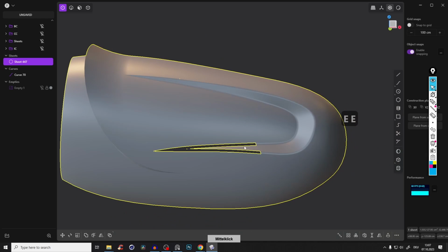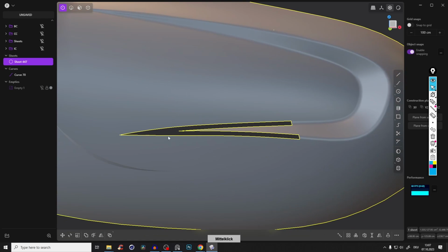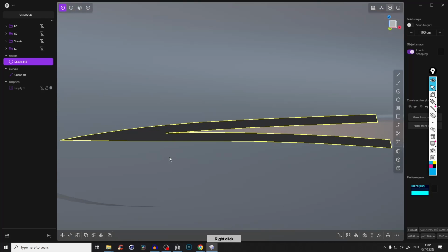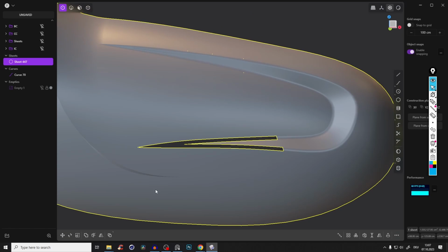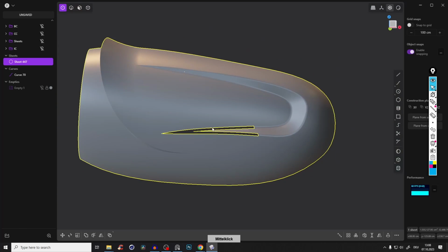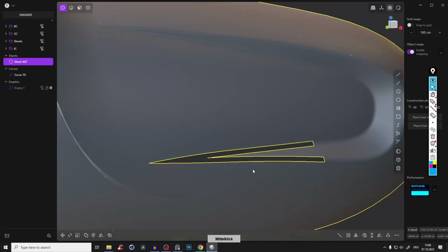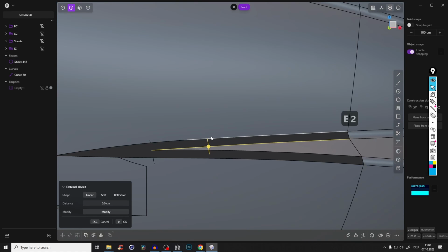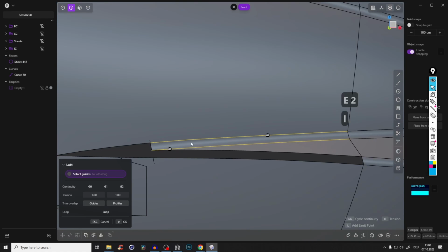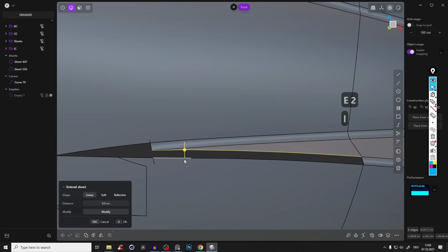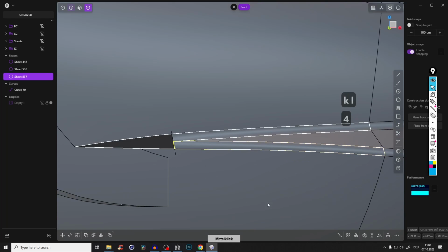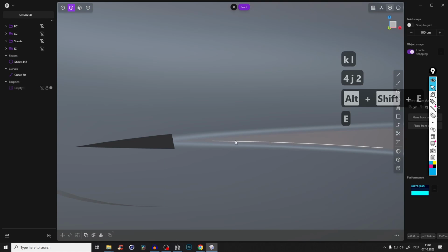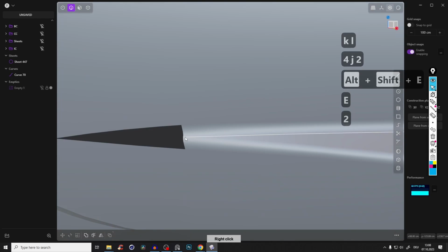So yeah, I mean, maybe you're wondering, like, why the heck should I do that? Because it worked before. Yes, if it works with just standard fillets, do that. But especially when you go complex, then you have to do it this way. So let's do the same here. Loft that and loft those edges as well. And amazing. Press 4, join everything. And you see it works out fine.